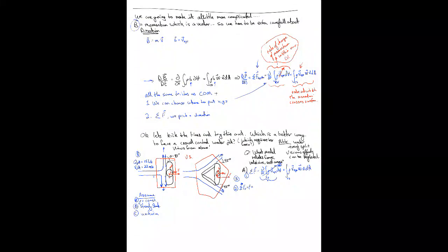So let's do our entrance. We have rho of our fluid times the velocity relative to our coordinate system of our jet, because we're worried about v, x, y, z now. It's actually 22 meters per second, but it's just going to be v jet, and that's positive because it's in the positive direction.